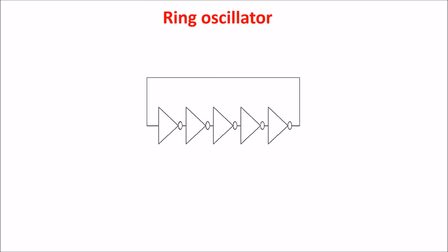The first feature of the ring oscillator is the logical instability. If we put a high value in the input, we have a low value at the end of the cascade, which is fed back in the input by the feedback, putting the input to low value, which in turn produces a high value at the end of the cascade, and so on. There is a combinatorial contradiction and the circuit is unstable.